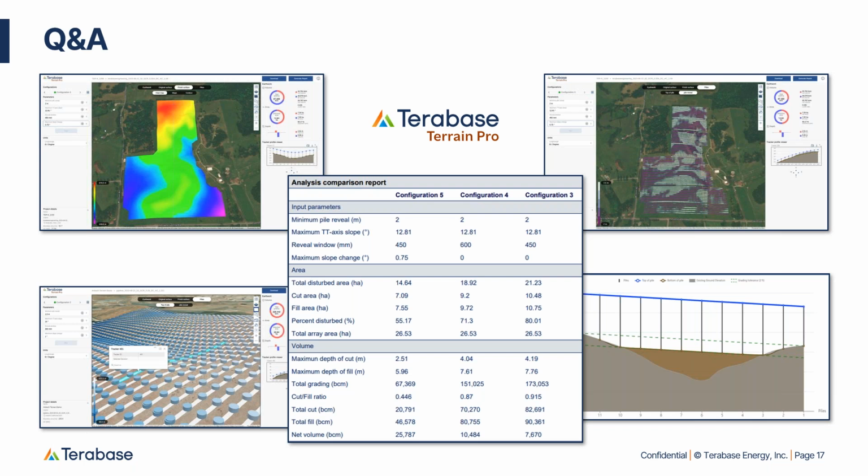Great. All right. So does this software take into account different tracker suppliers, or how would I specify different tracker suppliers when I'm using Terrain Pro or Design Pro? Yeah, great question. Tracker suppliers typically will supply their articulation angle limits and maximum torque tube axis slopes.